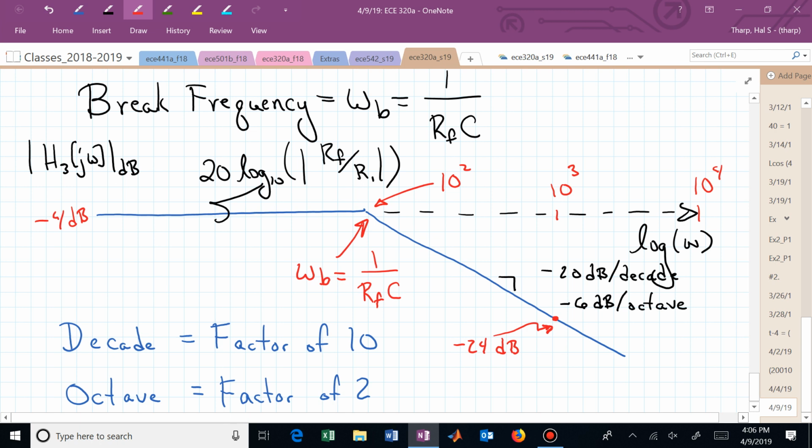It's not chop this up into equal parts and that will be 2,000. It's a logarithmic scale. So right here, if I could draw it, this would now be 2 times 10 to the 3, or that's now 2,000. I come over here, and what's the value of the magnitude curve at that point? It's 6 dB down from minus 24. This must be minus 30.